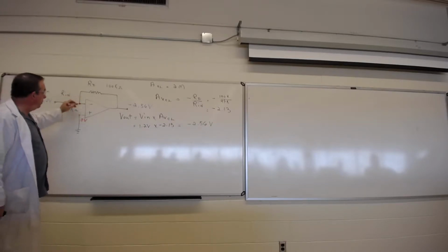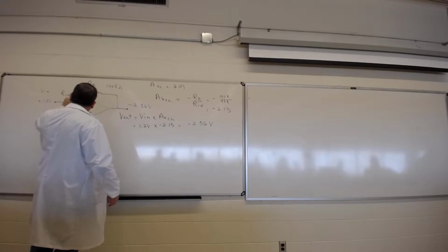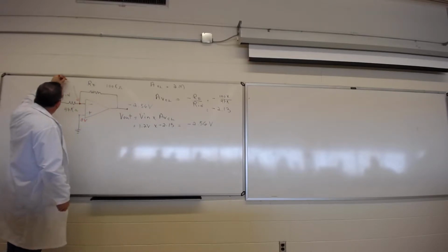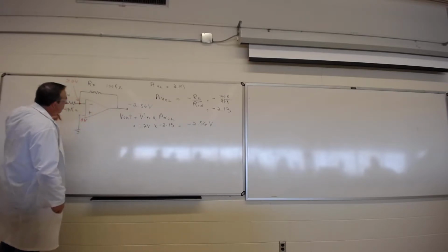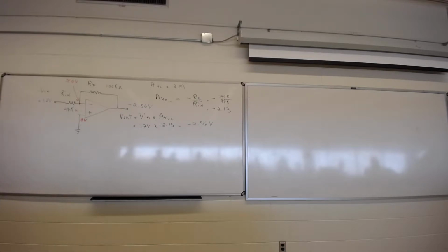This is why we say that the voltage on this particular input is almost 0 volts. That's what the negative feedback is trying to do. It's trying to drive that to almost 0 volts. Almost. We'll find out it isn't exactly 0 volts, but it's very close. Good? Yeah?